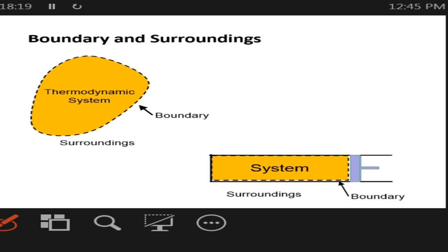So we talk about the boundary as what separates the system from the surroundings. Be very clear. This is the boundary. Sometimes students have a poor free body diagram, hence they can't solve the problem in statics or dynamics. Same in thermodynamics. If you don't have a clear concept of your system clearly defined, then you botch it. So the system here is shown to be the gas that's trapped in a piston cylinder apparatus.